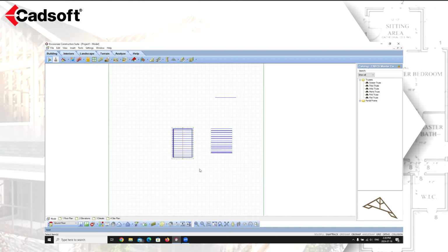We also give you the ability to add in truss runs, which will allow you to add in a truss run through a design. This truss run will recognize the roof surfaces, and it will also recognize any ceiling surfaces that you have, and it will cut the truss accordingly. We then looked at the timber profile option where you can actually insert timber framing, and it's going to give you a couple of different truss options.